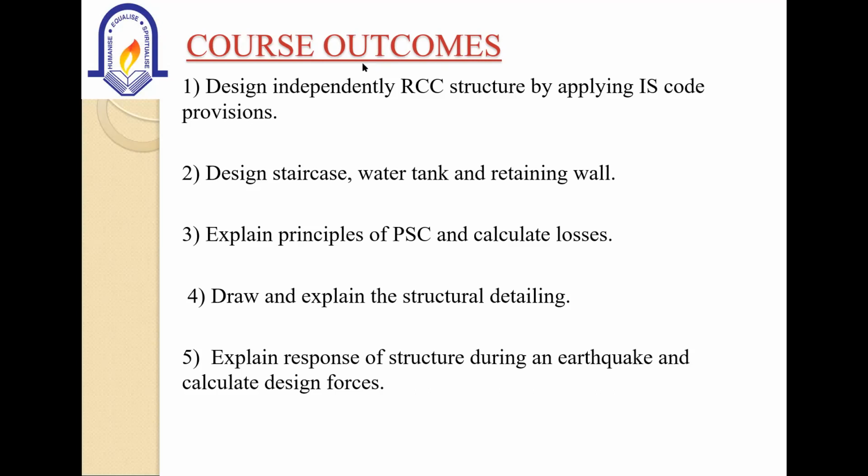In that you will come to know how your structure will behave, as well as you can calculate all the design forces based upon the earthquake. And for earthquake resistant design, you have to use a different IS code, that is IS 13920. You have to use IS 13920 for earthquake resistant design.